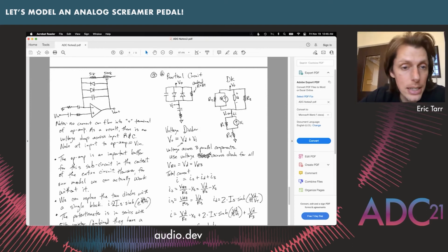Also, a thing that I'm doing is this potentiometer that is set up to control the distortion is done so that we have this wiper across the resistor that effectively just bypasses the resistor and allows us to just have 51 kilo ohms happening up here on this branch, or we can bring in more resistance on this branch too. What this is going to do, to give you some intuition about it, is the less amount of resistance we have on this path, the more current is going to be able to flow through this top path where there's no distortion, where there's no clipping that is going to happen through this one.